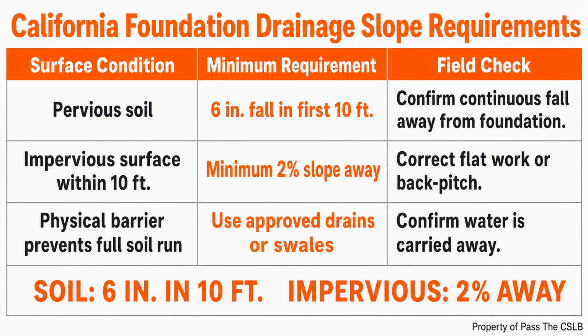If concrete pitches back toward the building, it collects and delivers runoff to the wall. In both cases, the field decision is to verify the direction and the amount of fall before the work is accepted or concealed by later landscaping.